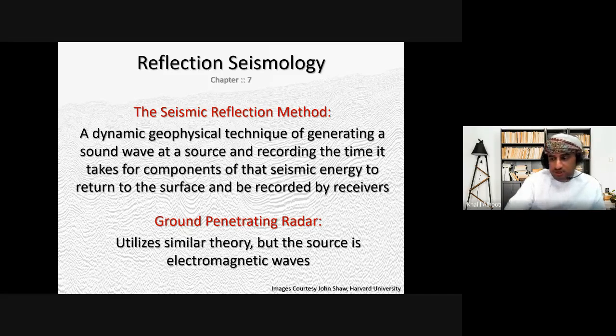They use GPR, but the antenna is in gigahertz. It's not mega, it's giga. It only goes deep up to 4 or 5 inches. Gigahertz cannot go very deep, but it gives you a very detailed image of the plaster. If there is a small bubble in the plaster, you can tell that there is a small bubble or the plaster is not made well.